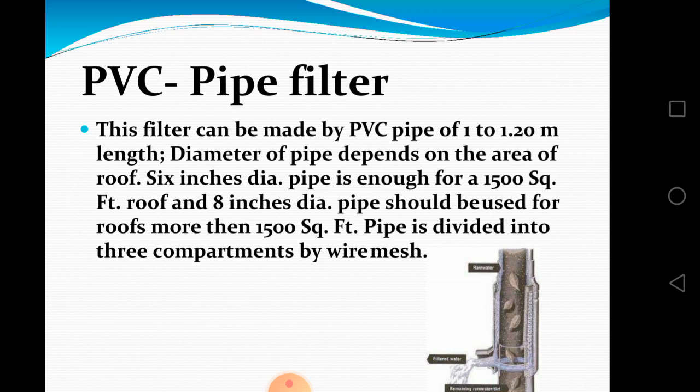When we design a rainwater harvesting system, we must see what the endowment is, and we have to identify the rainwater harvesting potential as far as the area is concerned. So rainwater harvesting potential is equal to rainfall times the collection efficiency.